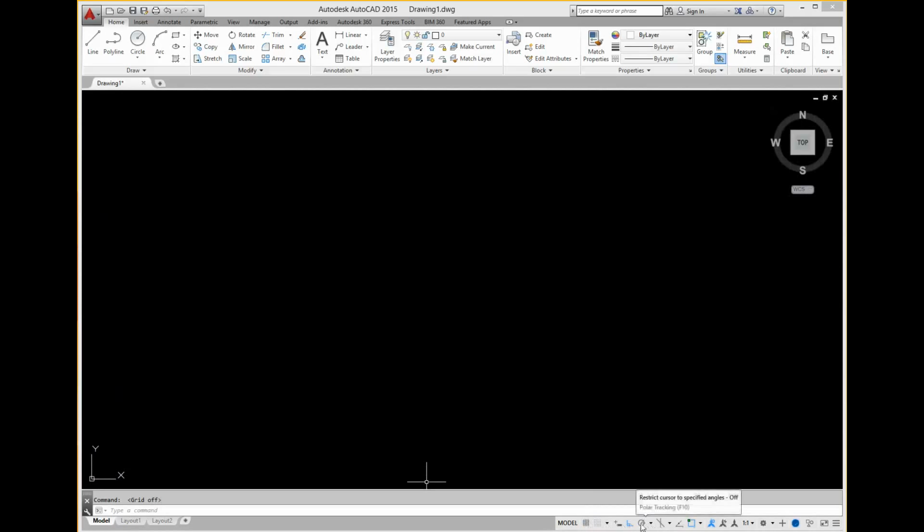Come over and find the ortho and turn that on, and then come over and turn on the O-snap and turn everything else off.